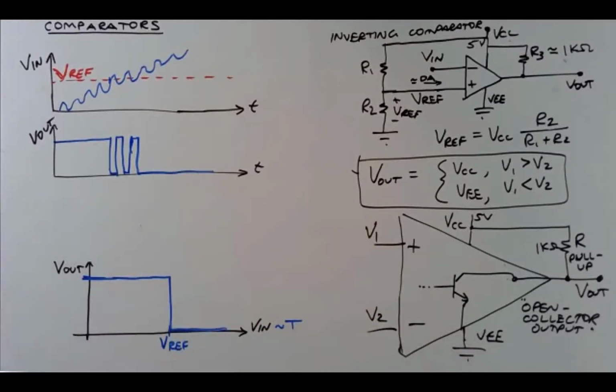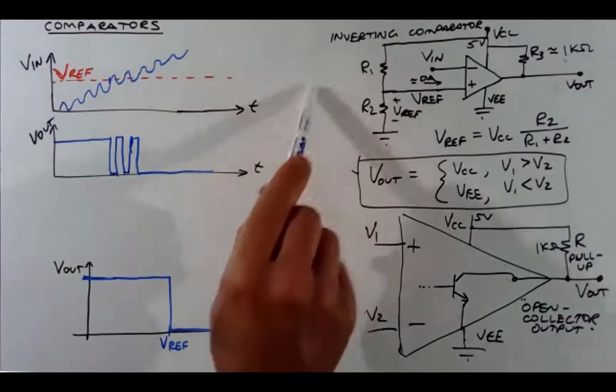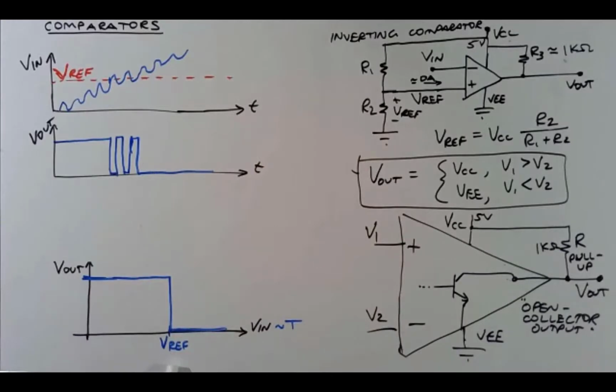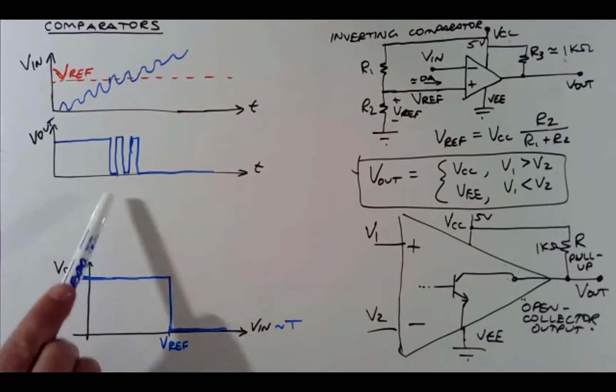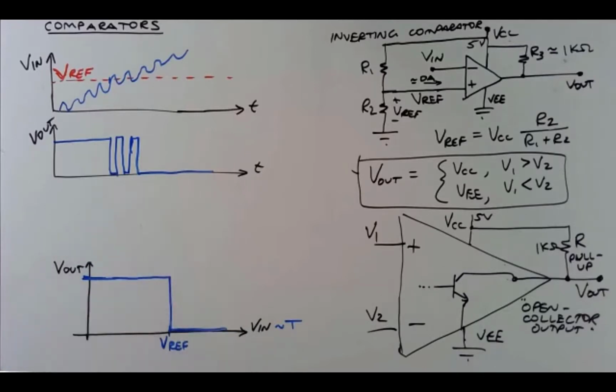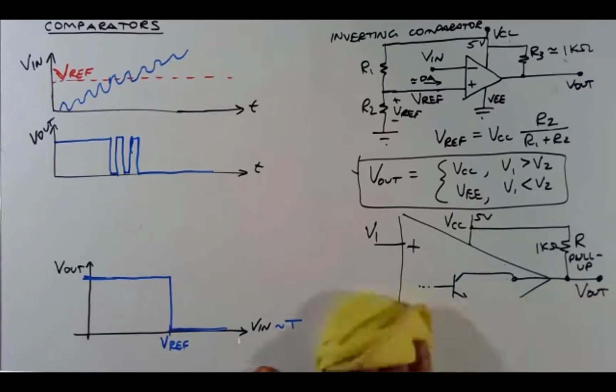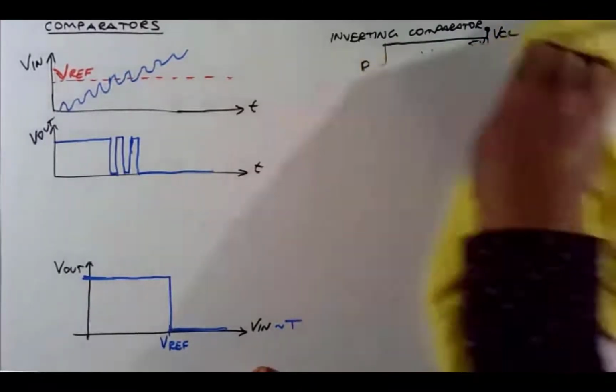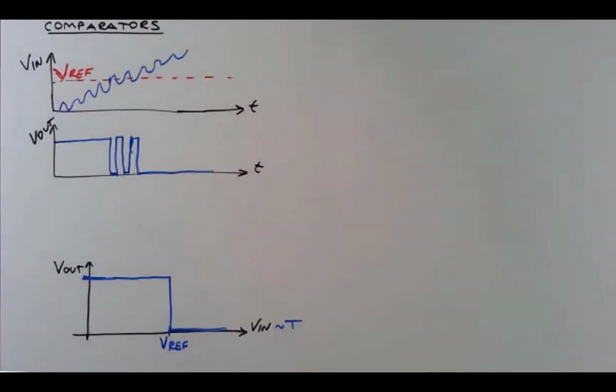So what you'd really like to do is have a different kind of circuit that has maybe 2 thresholds. The takeaway from this before we move on is that a simple comparator like I've drawn here with a single threshold, it's good, it's fine, it works, but it's not good in noisy environments if that matters to you. Okay, so let's create another circuit, actually another characteristic, and then we'll create a circuit for that.